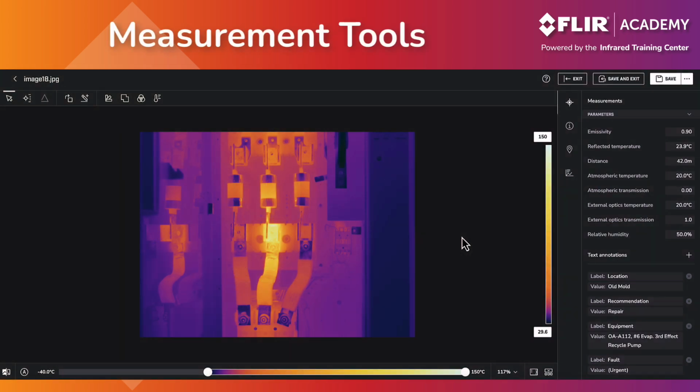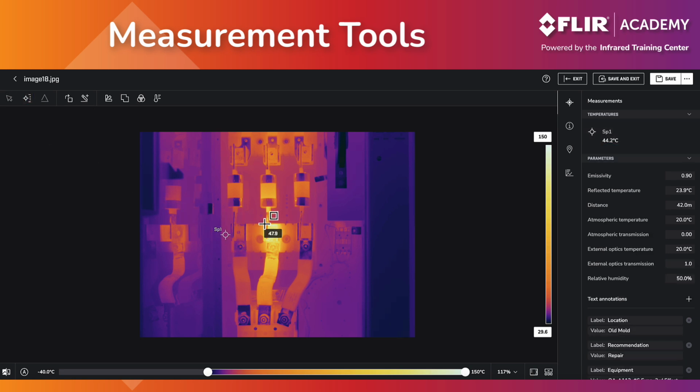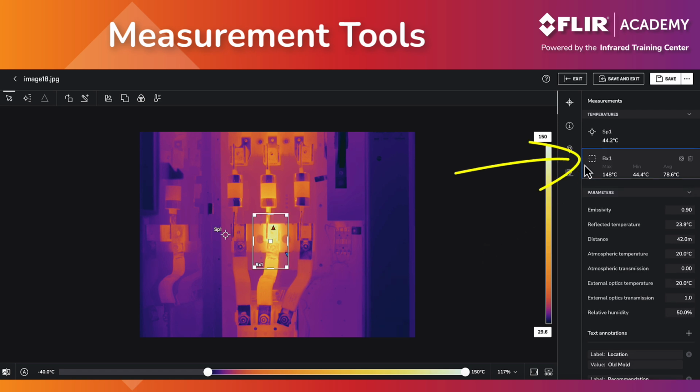Ignite provides a variety of temperature measurement tools that users can access from the measurement menu located here. These include a spot temperature measurement, an area box, an ellipse, and a line profile. Let's add a spot and an area box to demonstrate. As each tool is added, the temperature value for that particular tool is displayed here on the right. With the area box, you can see that the maximum, minimum, and average temperature values are shown.